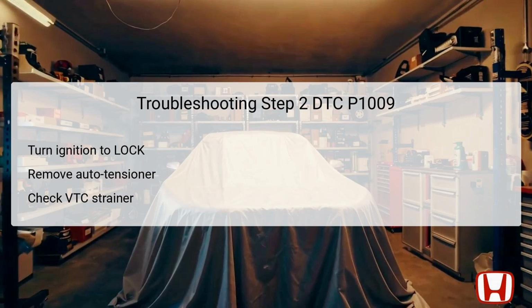If the strainer appears okay, the next step will involve testing the VTC oil control valve to further diagnose the system. Step 3 focuses on the VTC oil control valve operation check. After confirming that the strainer is clear, the next task is to test the VTC oil control solenoid valve, ensuring it operates correctly under various conditions.